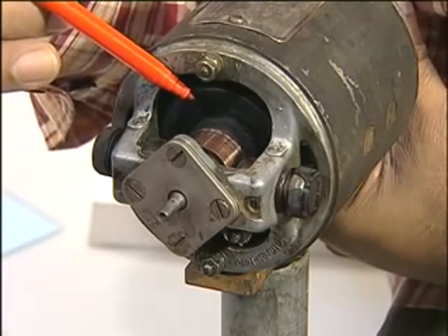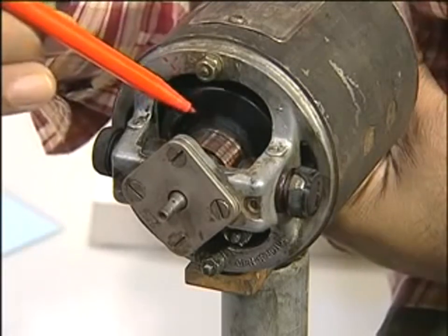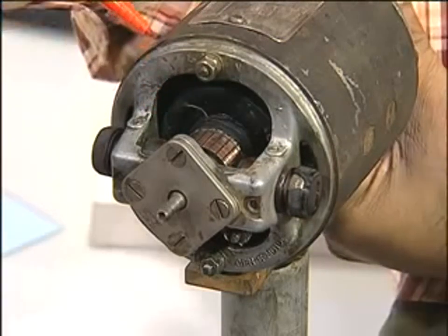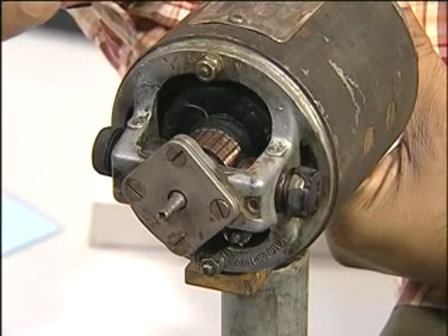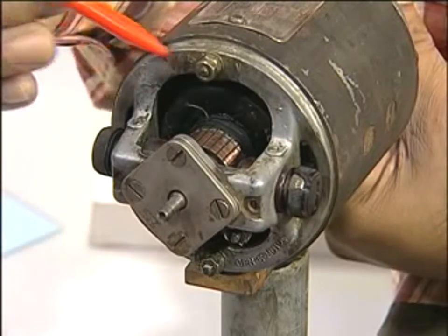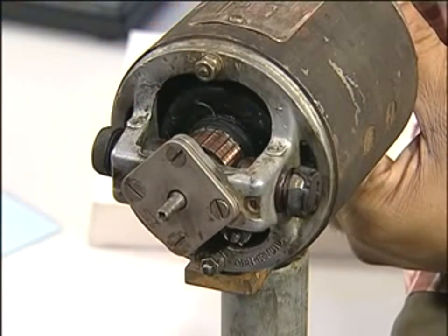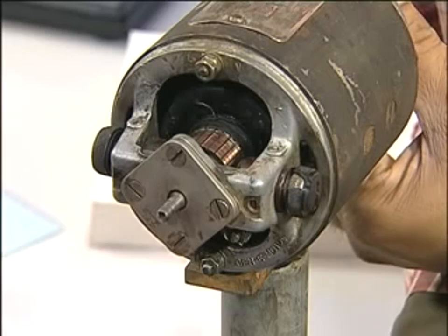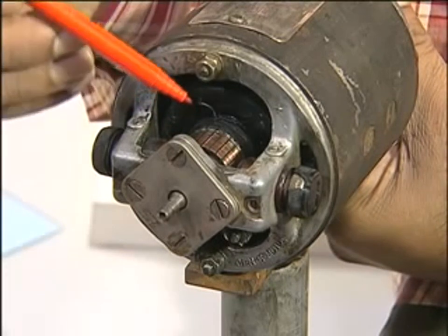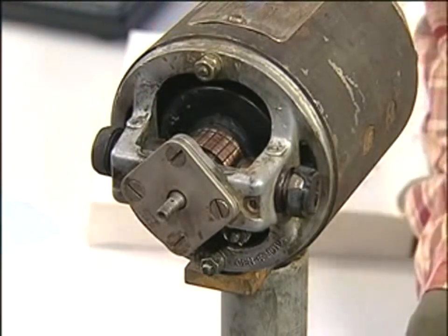And this is a 38 slot motor, and therefore you have much less ripple as compared to a 2-slot or a 4-slot motor that we just saw. 4-slot meaning you have 4 slots on the rotor with 4 coils. 12 slots means 12 coils. 38 slots means you have 38 coils in this one.